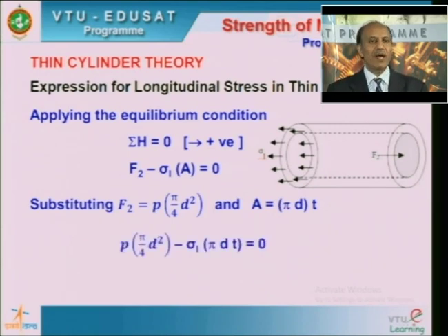You need to simplify this and then you get a very simple expression, very similar to that of your circumferential stress. The expression we have got here is P d by 4T. If you look at this expression, you can easily understand, as the internal pressure increases, the longitudinal stress increases.